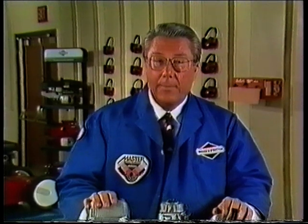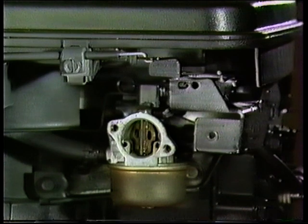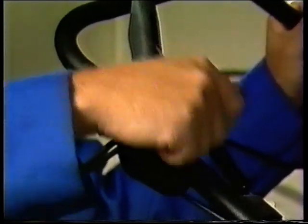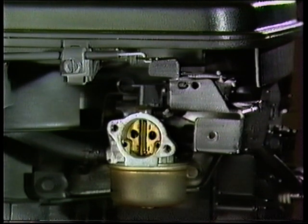Check the choke adjustment. This is a source of trouble more often than you might think. In some cases, a carburetor has been removed, cleaned, inspected, and reinstalled, and it works fine after that, even though the technician found nothing definitively wrong with it. What's probably happened is that the choke, left partially open before, is now adjusted properly. So, checking the choke early in your troubleshooting can be a big time saver.